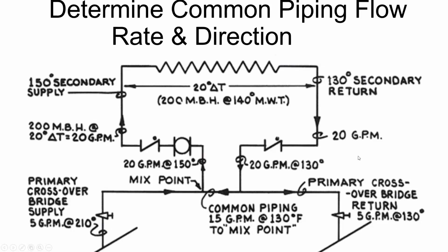Yeah, exactly. And then I'm going to look at the supply temp, and then I might even have an outdoor air sensor that says, hey, is it 40 degrees, 25 degrees out, 5 degrees? What is it? And I'll constantly be repositioning to change that supply temp to do an outdoor reset. But yeah, I could use a 3-way valve and adjust accordingly. So if it starts to overheat, some of that water might go through the bypass, it doesn't get directed up here.